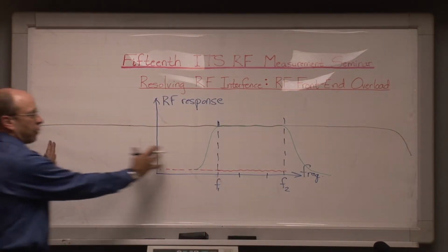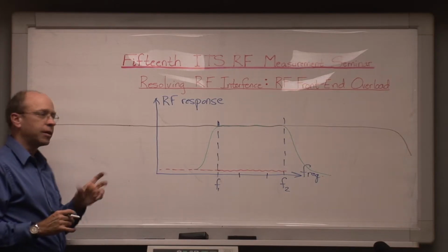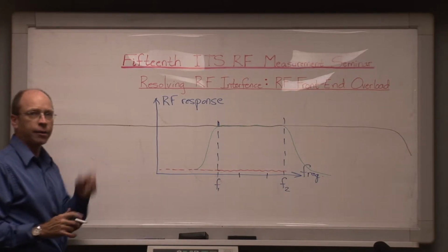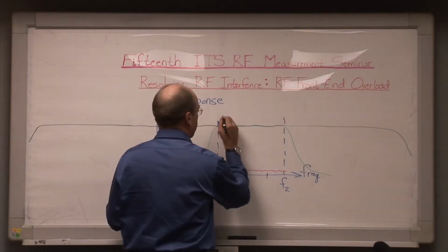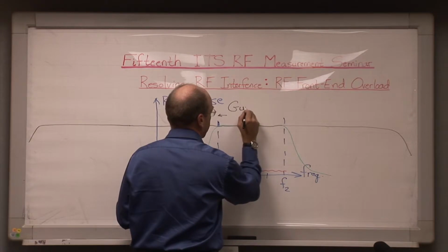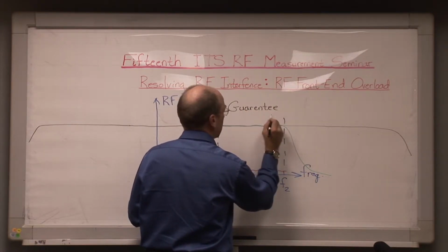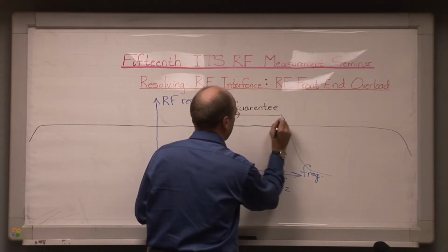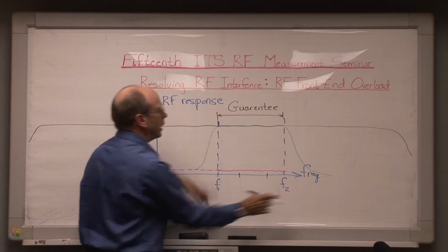And you say, well, wait a minute, why does it have such a wide frequency response range? It said F1 to F2, maybe, for example, 3700 to 4000 megahertz on the package. The reason seems to be that manufacturers typically guarantee, the word is guarantee, that it will produce those noise figure and gain responses across that range from F1 to F2.